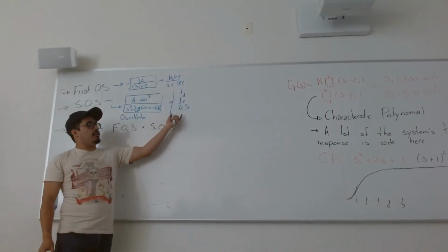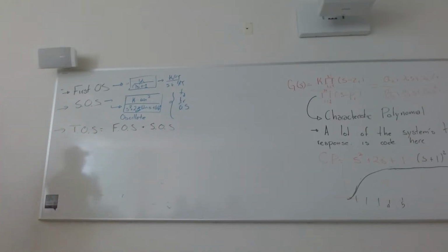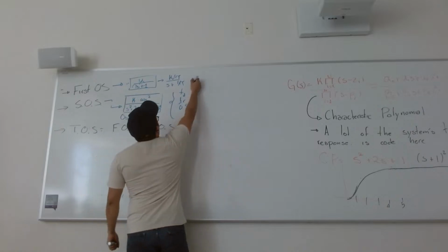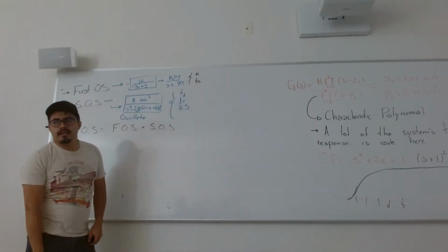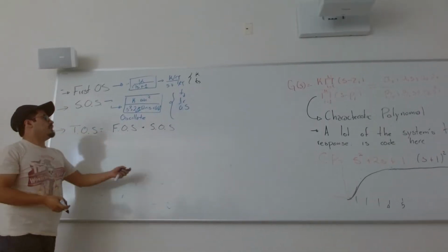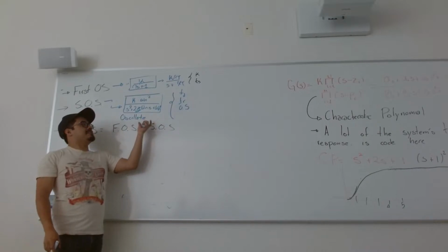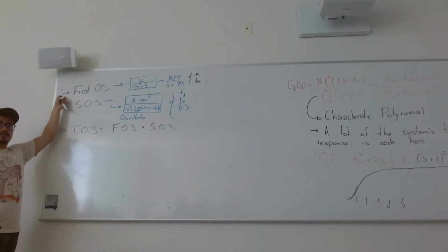These values are only the same time. I can calculate that even if it's a second order system with real parts. Okay, here I only have gain and settling time. I can calculate that. The gain, the settling time, and because I can calculate the settling time on a first order system, if this doesn't oscillate, I can still calculate the settling time. Okay, I can still calculate the gain of the system because those properties are shared with the first order system.